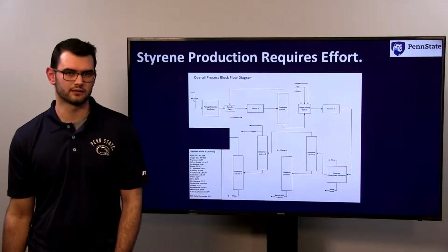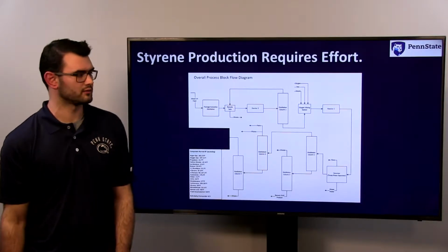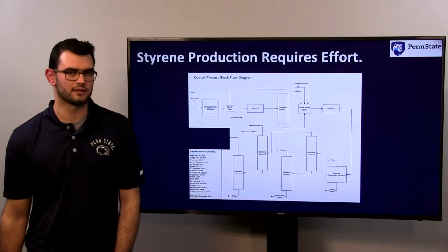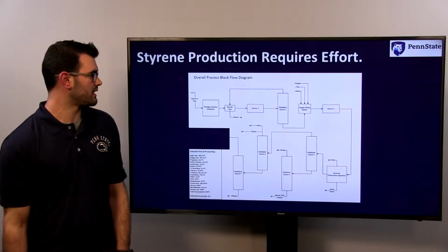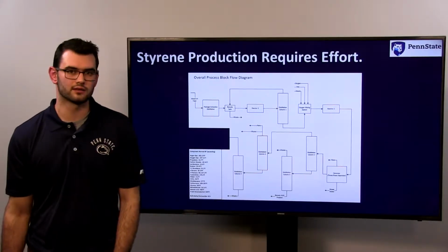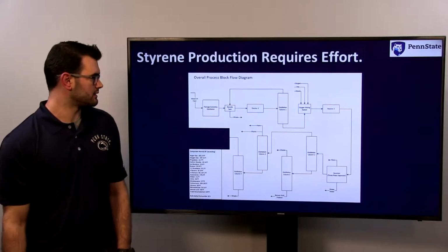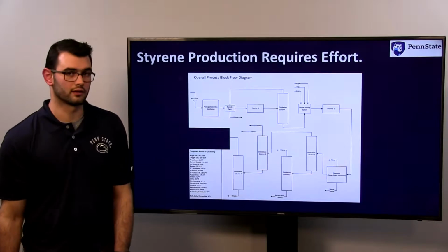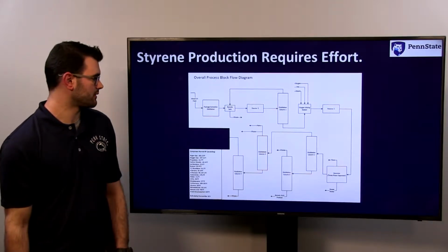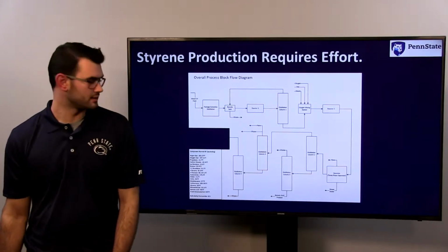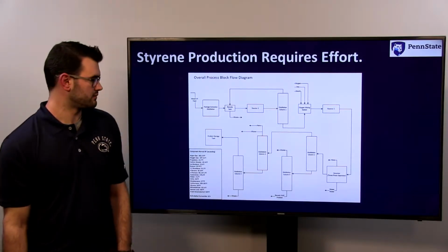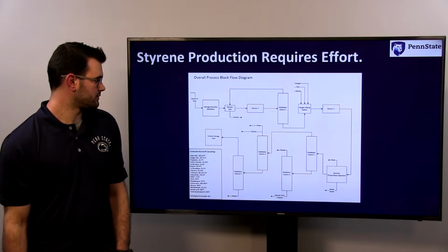The reason why the reflux ratio is so high is because we're not concerned with the flow rate or any technical details of the distillate, as it's mainly a waste stream and another stream that is sent to a flare. This is done through a partial condenser in order to limit the liquid flow rate in the column from being astronomical.